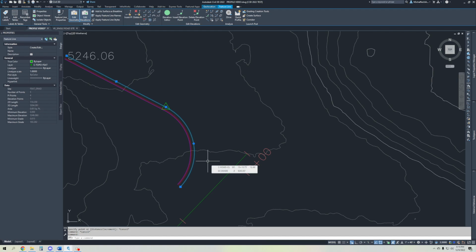A lot of times when I have a return or like the curve between one section of road to the other section of road, I like to add in these intermediate points between the two PIs that I typically have, because that just allows my finished grade surface to triangulate just a little bit better, adds more points and makes a smoother surface.